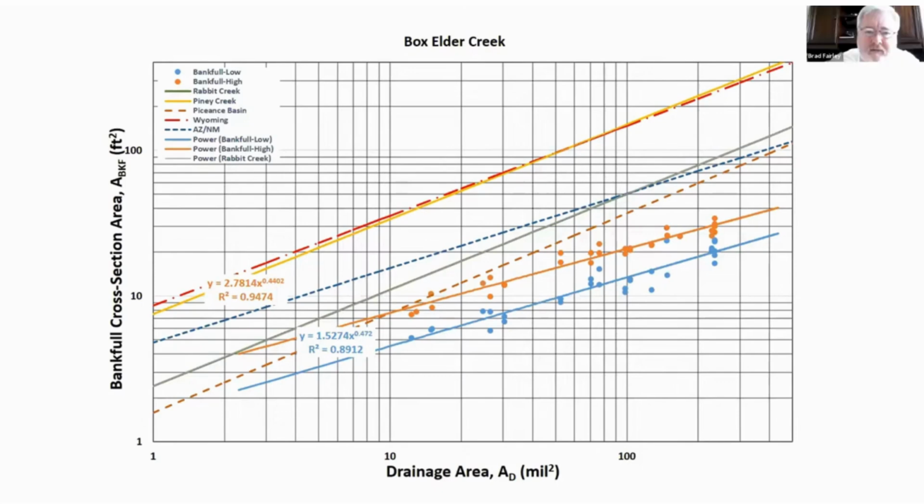So, Mike, I've got a question. When I look at the two curves, it looks like it's pretty consistently undersized the entire length of the channel. Yeah, it is. It doesn't look like there's a local pumping effort that would create a problem in a specific location. It seems to be a consistent issue the entire length of the watershed. So is it essentially a losing reach its entire length? I mean, that's what it would suggest. Yeah, it definitely could be.